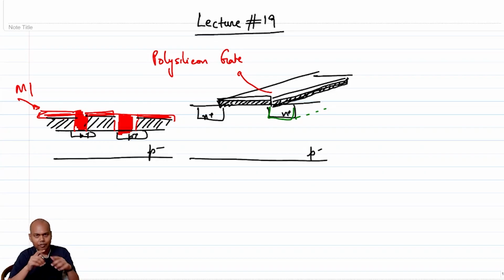And you cannot ever afford a crisscross between two nodes, otherwise they will get physically connected. So in order to avoid physical overlap while connecting between nodes, and while ensuring that you do not have to go all around the town to connect point A to B, what you need is essentially more metal layers.